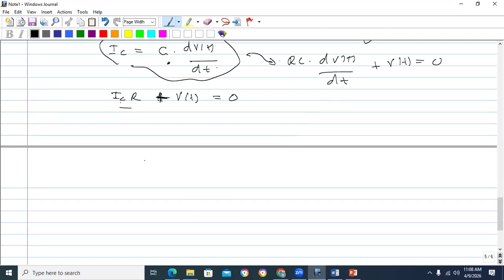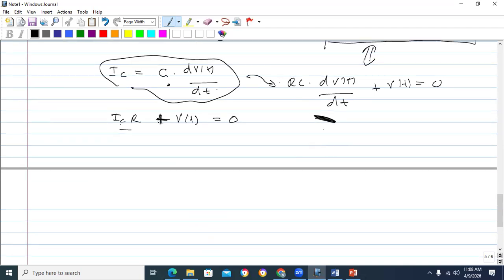And so solving the differential equation, actually, I think we can do it in the variable separation method, no? So here you have V(t). Here you have dV/dt. The RC is there, equal to minus V(t). Okay. So you can get this one here and this one there.